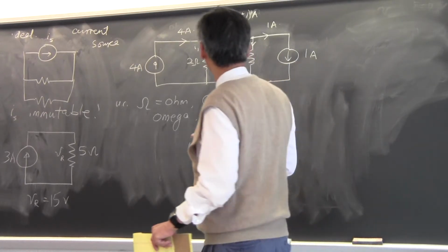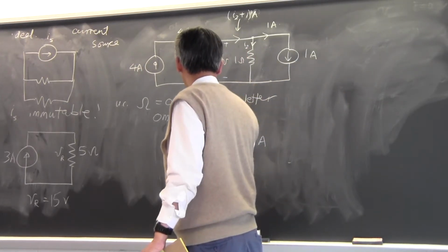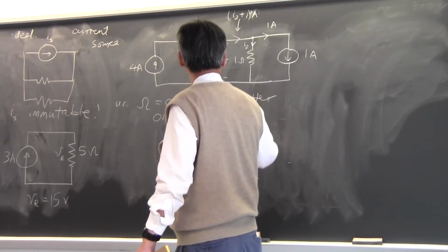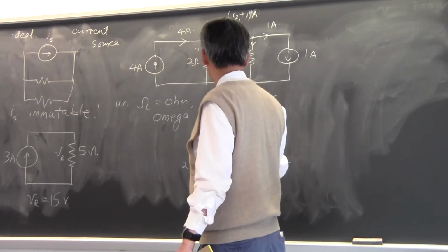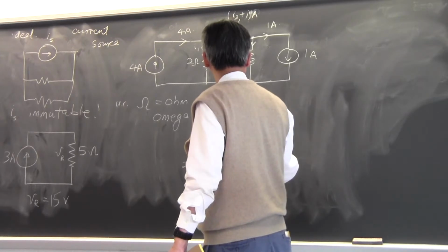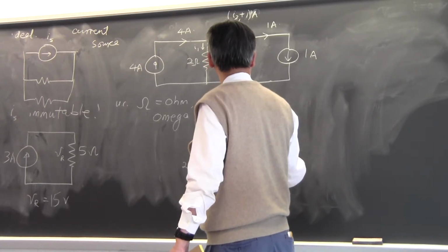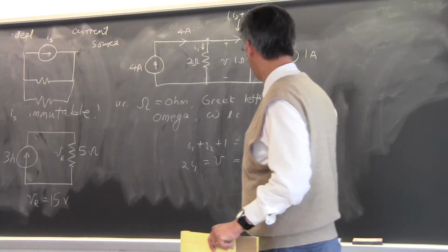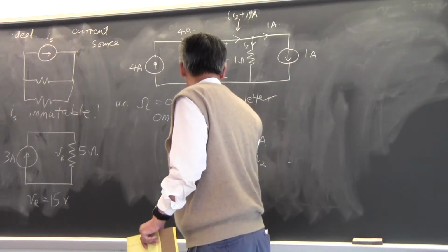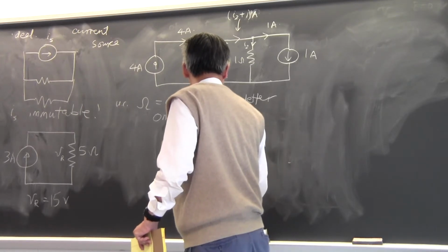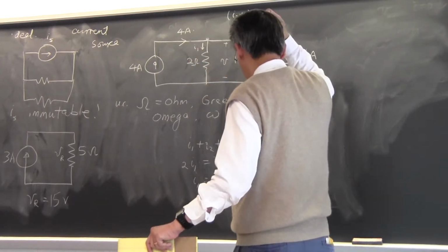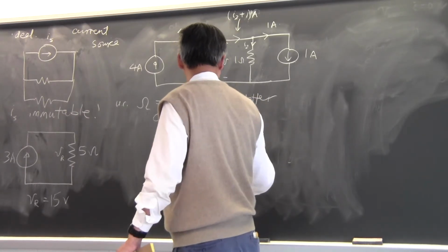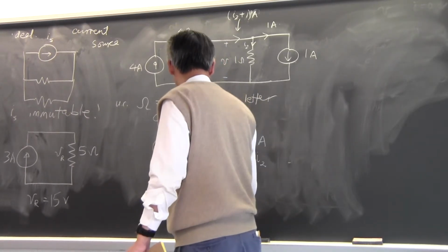And then I have this requirement that I1 times 2 must be equal to V. Since this is the same voltage drop for both resistors, it must be 1 times I2. So you have two equations and two unknowns, being that I1 must be equal to half I2. Then you can substitute into the first equation, or you can say I2 is 2I1, doesn't matter.